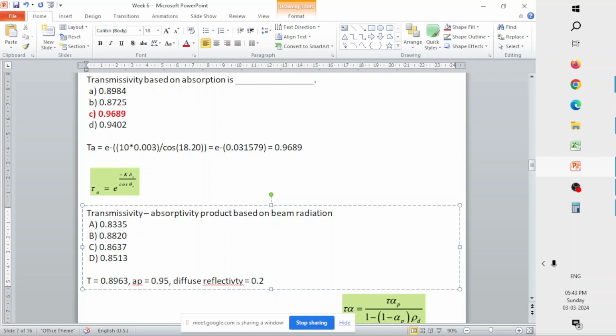Since the diffusive radiation gets scattered by the atmosphere, they will be traveling in all the different directions. So it is not possible to account for every single diffusive radiation that falls onto your flat plate collector, because each and every one of them will be at a different angle. So we take the value of theta as 60 degree and calculate. Similarly, for diffusive reflectivity, in these cases the rho d value we take it as 0.2 and then we solve for the system of this equation.